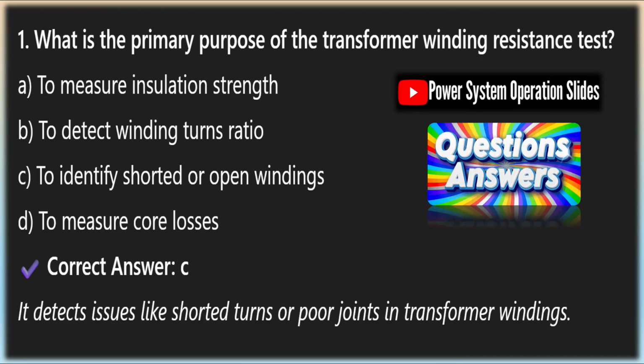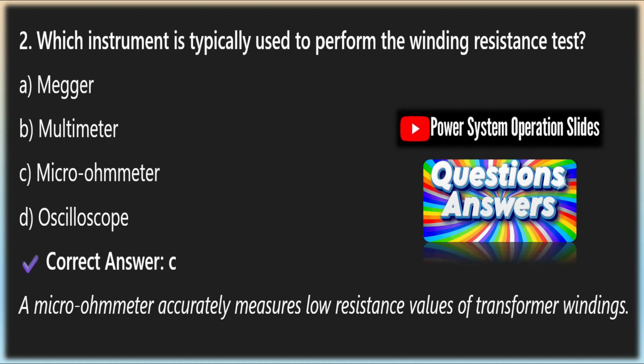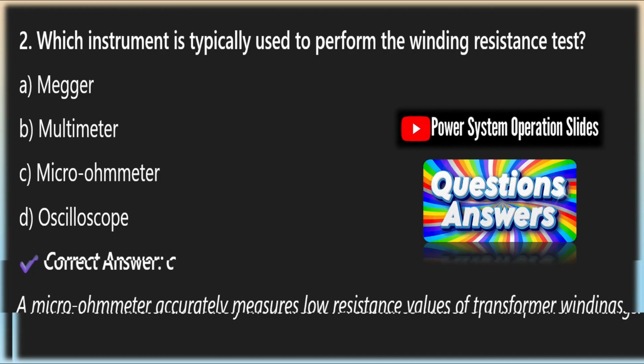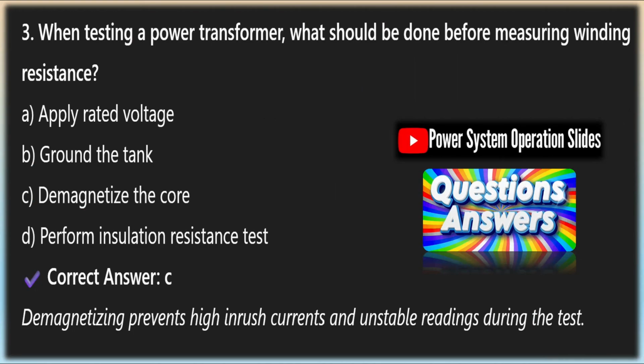Thermal equilibrium of the transformer is important to minimize transient effects during winding resistance testing. If the transformer has been recently energized or heavily loaded, it is advisable to allow sufficient time for the windings to cool and for the oil and metal temperatures to stabilize. Ambient temperature fluctuations during test execution can also introduce variability in resistance readings. Scheduling testing during periods of stable environmental conditions reduces the need for extensive compensation and improves repeatability.